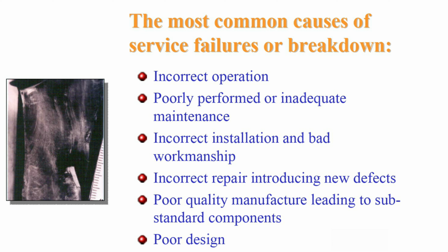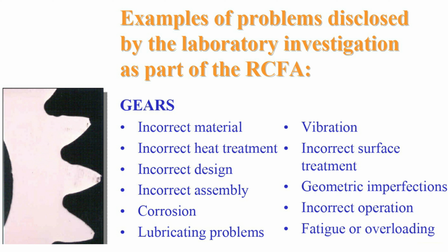Examples of problems disclosed by the laboratory investigation as part of the RCFA: gears. Incorrect material, incorrect heat treatment, incorrect design, incorrect assembly, corrosion, lubricating problems, vibration, incorrect surface treatment, geometric imperfection, incorrect operation, fatigue or overloading.